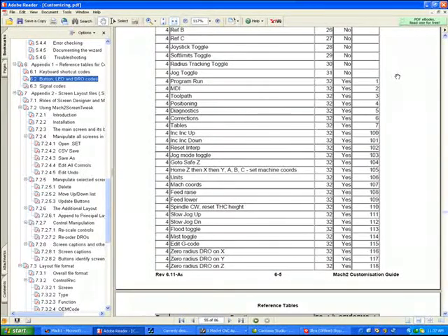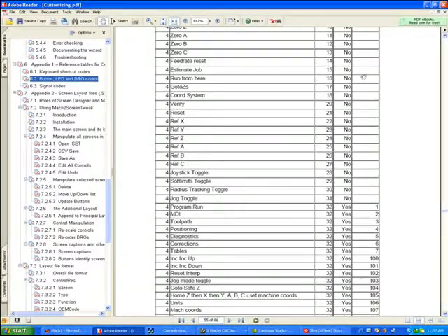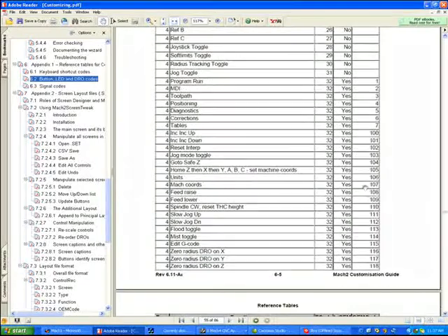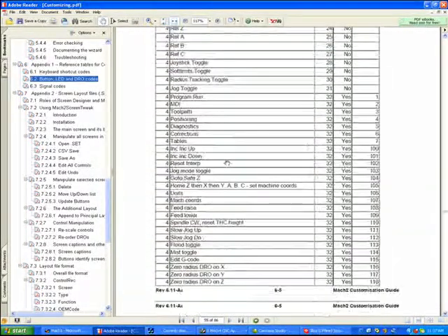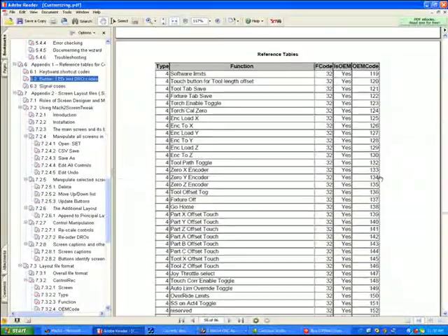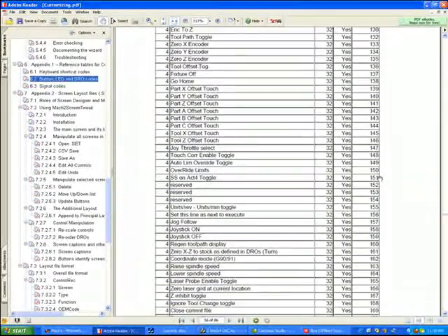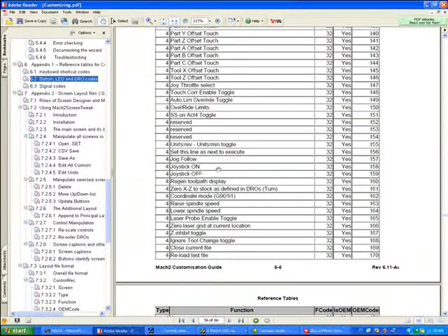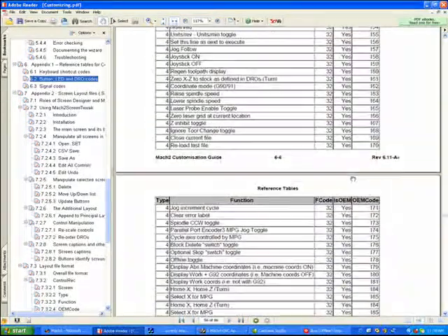Most of the time you'll be sticking with the ones that have entries in the user DROs, such as Go To SafeZ, which is a button, and you can call that by saying DoOEMButton(104). Here we have joystick on, which would be DoOEMButton(158), for example.